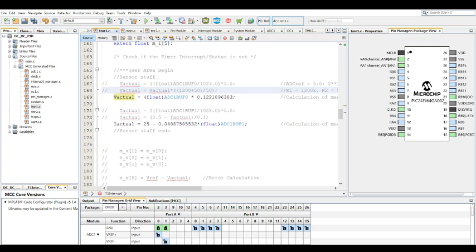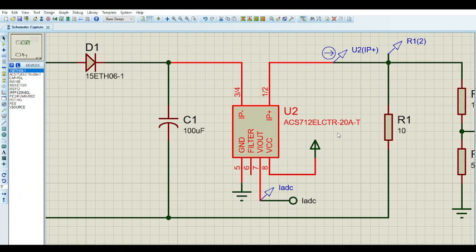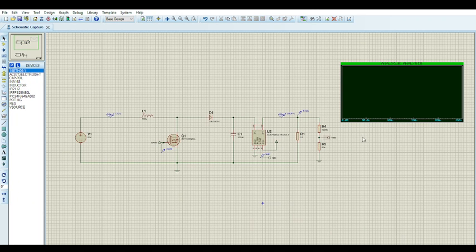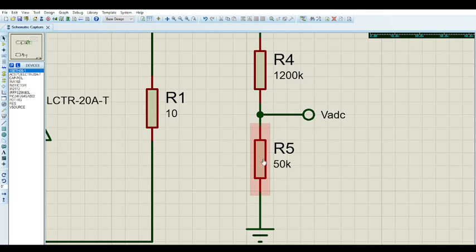Another thing I want to take note of: if you're doing something like this, you want to make the smallest resistor quite large, like at least 50K. If you're really trying to push it, 10K. Anything below 10K for the small value, I don't advise that. Try to make the smaller one a bit larger because you don't want your sensors to start taking power away from your converter.